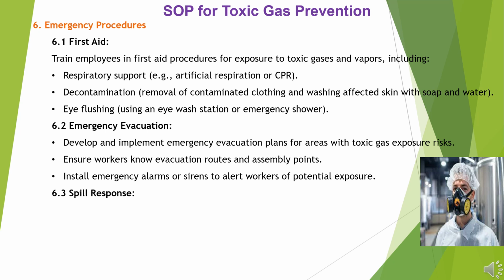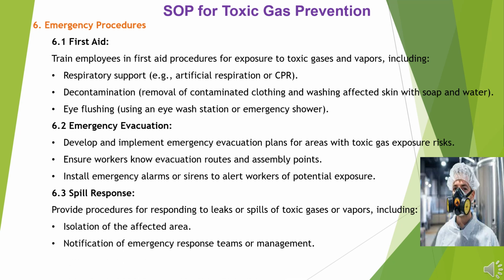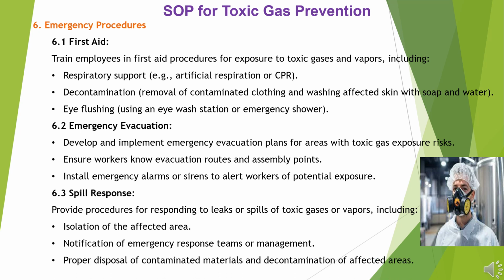6.3 Spill response. Provide procedures for responding to leaks or spills of toxic gases or vapors, including isolation of the affected area, notification of emergency response teams or management, proper disposal of contaminated materials and decontamination of affected areas.